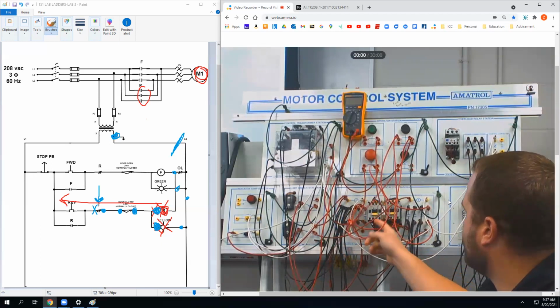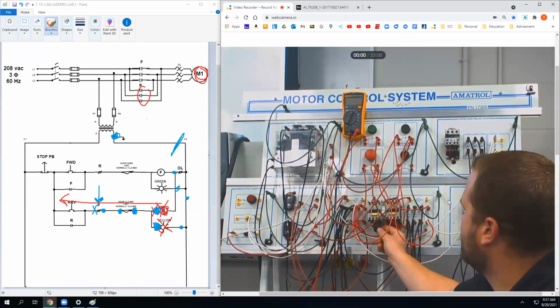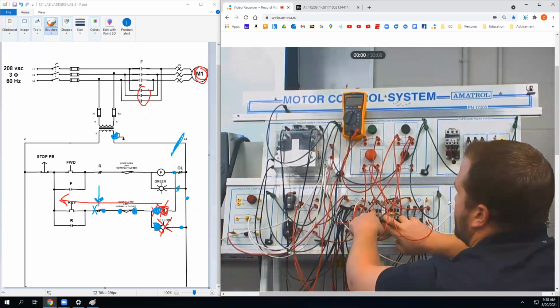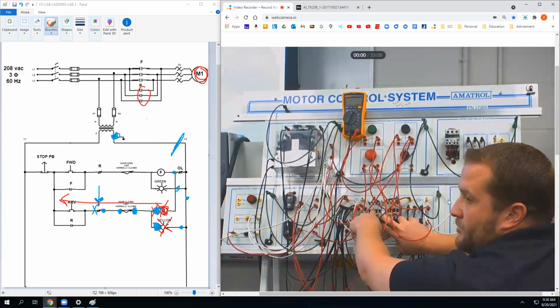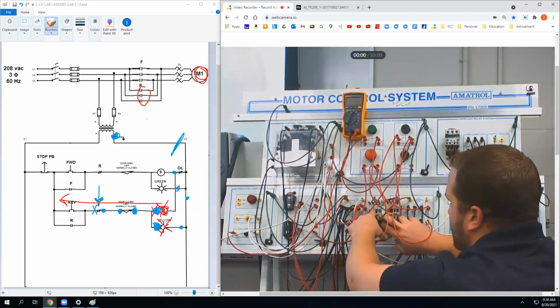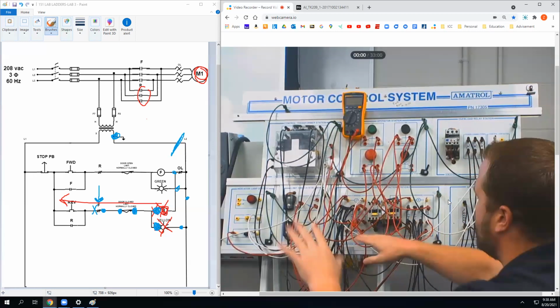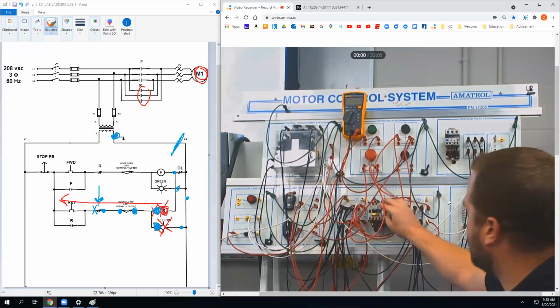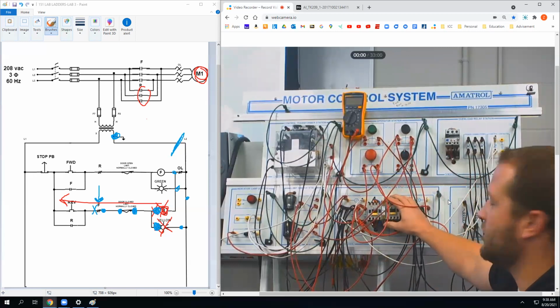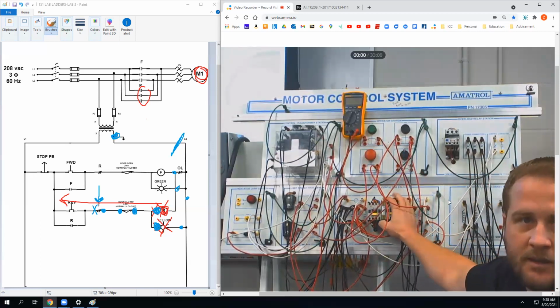In real life, you pull these wires off and put your leads on there to check continuity and push that coil in. When I do this, I should hear a beep, right? So I'm suspecting that we would go like this and not hear anything. Then you know, okay, there's something going on with this contact. Pull that contact off, get a part number and replace it, okay?